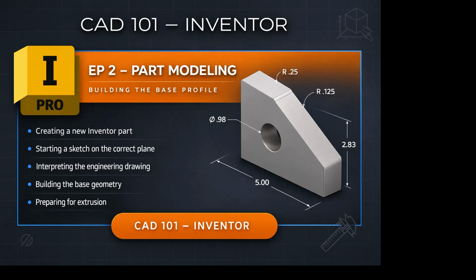So again, when we go over to Inventor, we're going to start by building the base profile. And that means creating that overall shape, identifying the key dimensions, and then sketching the geometry so it's fully constrained. Once the sketch is stable and complete, we'll be ready to turn that 2D sketch of that front face into the full 3D feature.